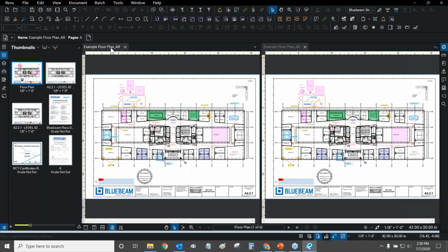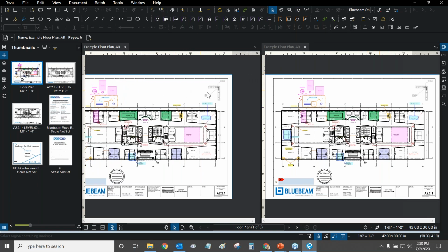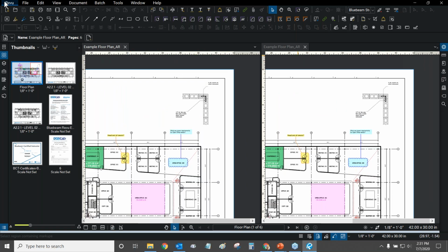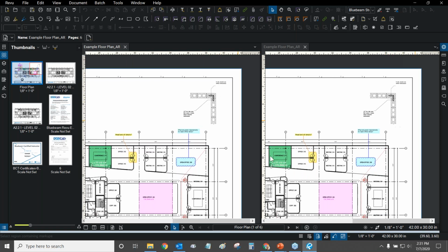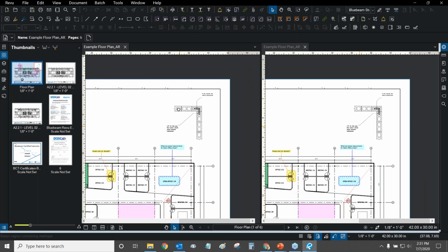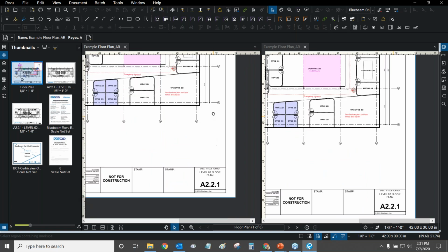All right, so now I've split my screen. And now, if I wanted to, let's say that I navigated on one screen, the other one is moving with it. And that's because in our preferences, we've already set ourselves up to synchronize by page. So what does it mean to synchronize by page and synchronize by document? Let's go to our drop-down next to the synchronize button right here, and we're going to change it to document, and I'm going to show you guys what happens. So nothing seems to have happened. Everything seems normal. Wherever I navigate on one side, the other side follows.